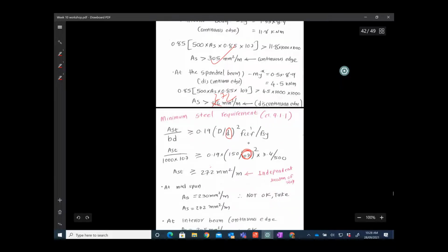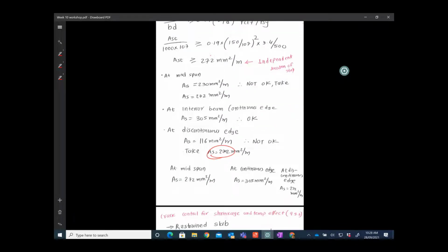So that is how our beam slab will not have any collapse. The brittle failures will not happen. It will stay there. It will have ductility, meaning that look, the failure will happen, but it will not be sudden failure. Okay.